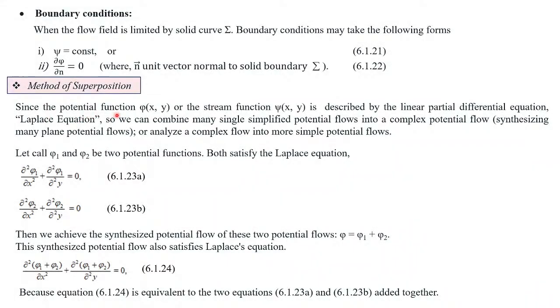Since the potential function phi and stream function psi are derived from the linear partial differential equation, the Laplace equation, we can combine many simple potential flows into a complex potential flow, synthesizing many plane potential flows, or analyze a complex flow into simpler potential flows. That is called the superposition method.